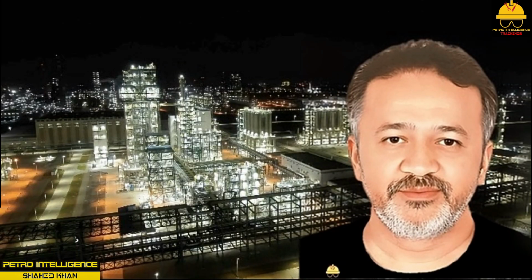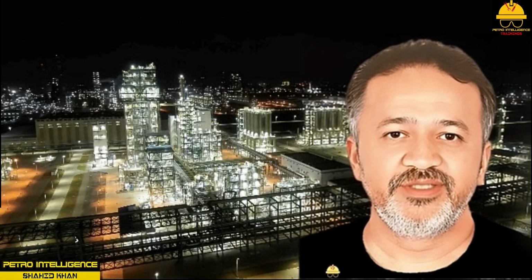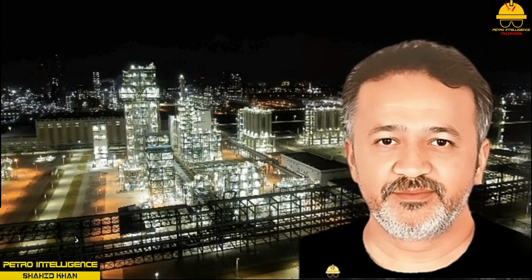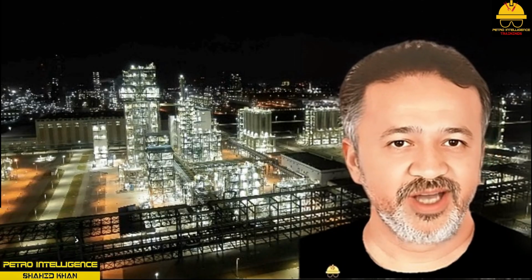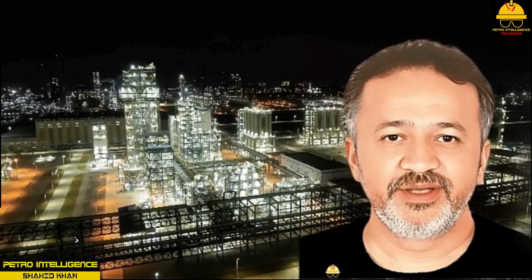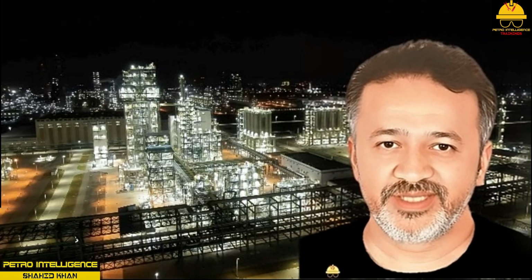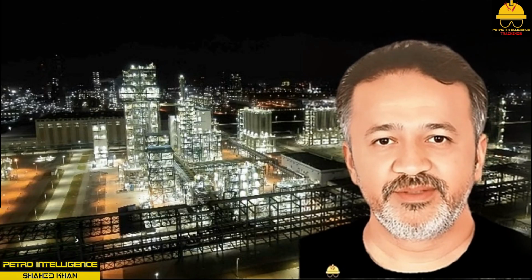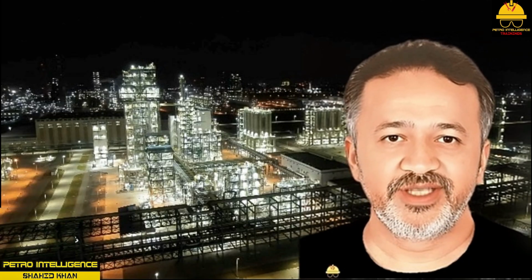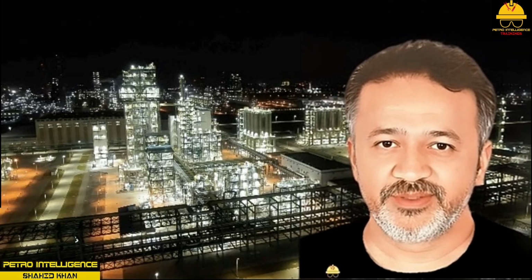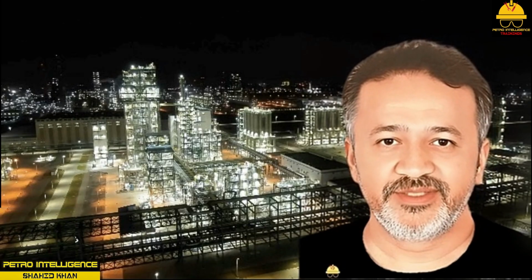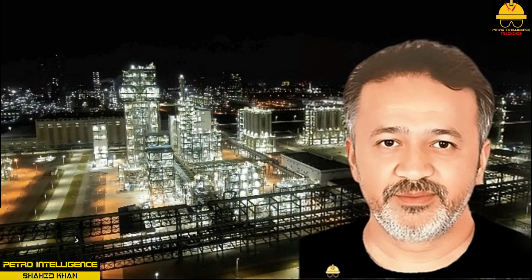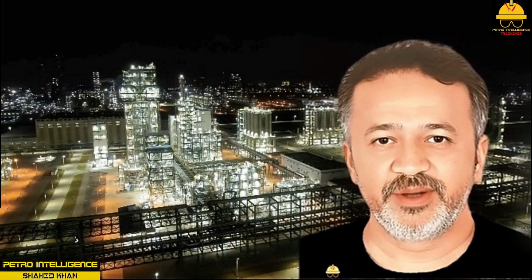Pressure control loop. A pressure control loop design uses the 5 elements of the control loop. The area to be controlled is a special vapor disengaging cavity that allows vapors or gases that are compressible to be controlled at a set point. The one area that changes consistently is the first primary elements and sensors. Pressure-controlled loops use devices to detect pressure changes. These primary elements are typically expansion-type devices. Primary pressure elements include Bourdon tubes, helical, spiral, bellows, pressure capsule, or diaphragm.